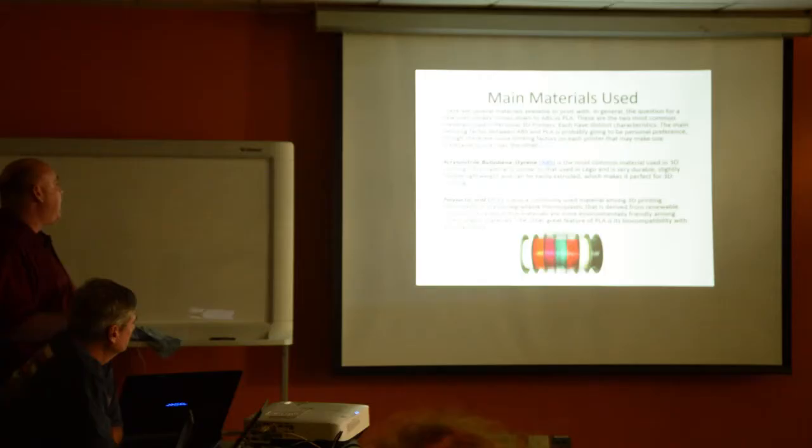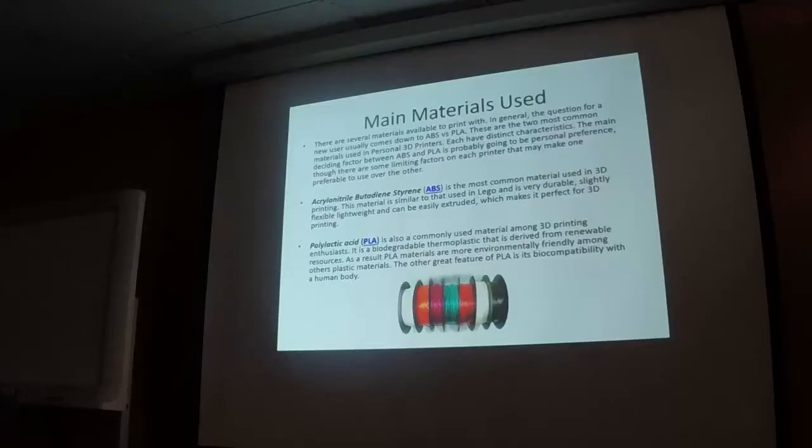And then we've got PLA, which is another commonly used material. It's biodegradable, so that's why I haven't used it, because its UV rating properties aren't very good. I've used it generally to make clips for the lighting to be held on catenary wire and things like that. So black ABS was the choice, because black helps add UV properties, because black is a carbon-based colour, so inherently it adds UV properties.